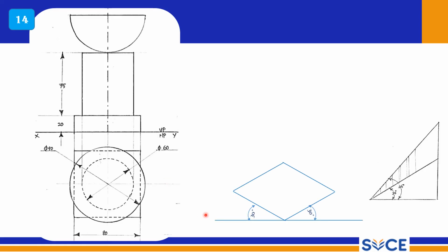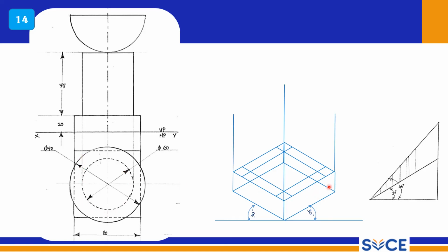So this is the converted dimension. This is the isometric scale I have used. So now we are drawing the isometric projection. This is the block, say the prism. On this prism, draw the circle within this. You draw the circle, you draw the square for this circle. Now with the given height, draw one more circle on the top to accommodate this circle.